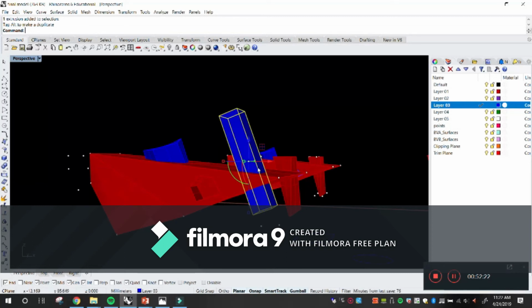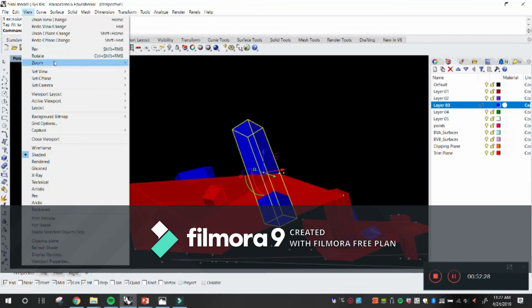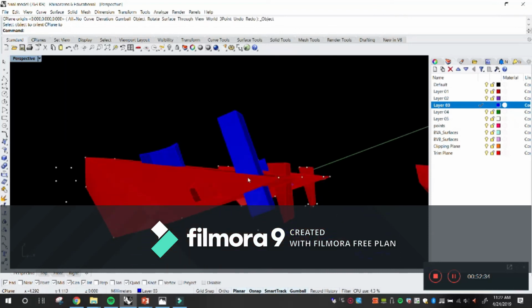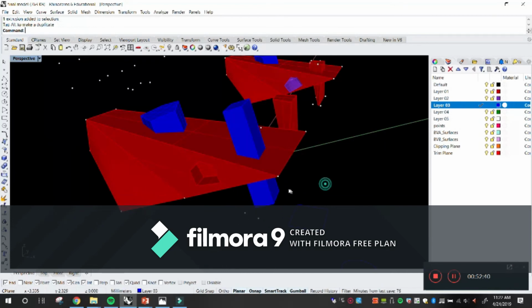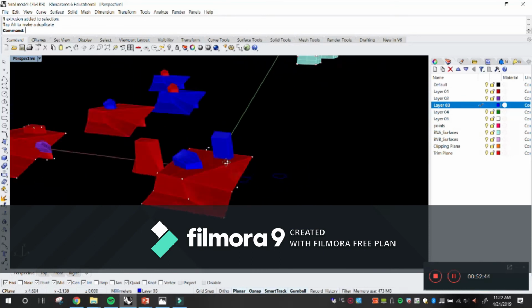Again, if I just want to slice this through its axis, well, we need to set back the C-plane. So View, Set C-plane, Object. Again, that's the object right there that gives us the plane. Now notice the gumball, how it changed. And now you can slice it through it. And you can do that through any face.